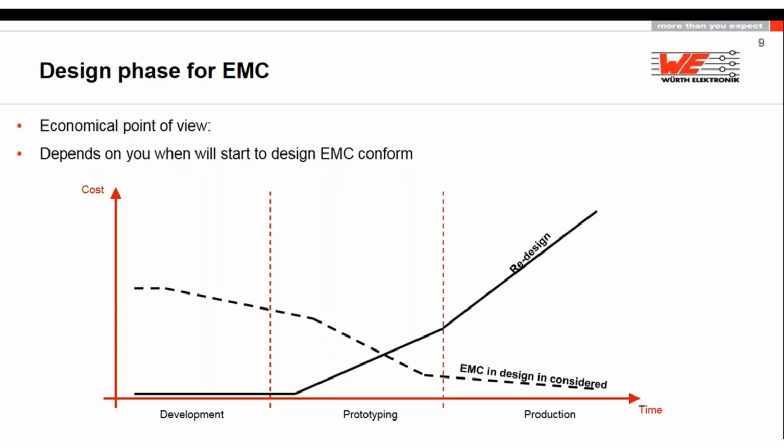When you know that you have a very fast rise time on some signal, or high currents, or you know the switching frequency of your DC-DC converter, you should take care about what happens with the harmonics and which kind of filter you have to design for this switching device. Sometimes problems in EMC happen because you're not thinking about the harmonics, or because you're not thinking that you will need a filter anyhow, or you want to save money on the filter and then you put a very expensive solution outside of the box with snap-on ferrites, or you have to modify your complete shielding.